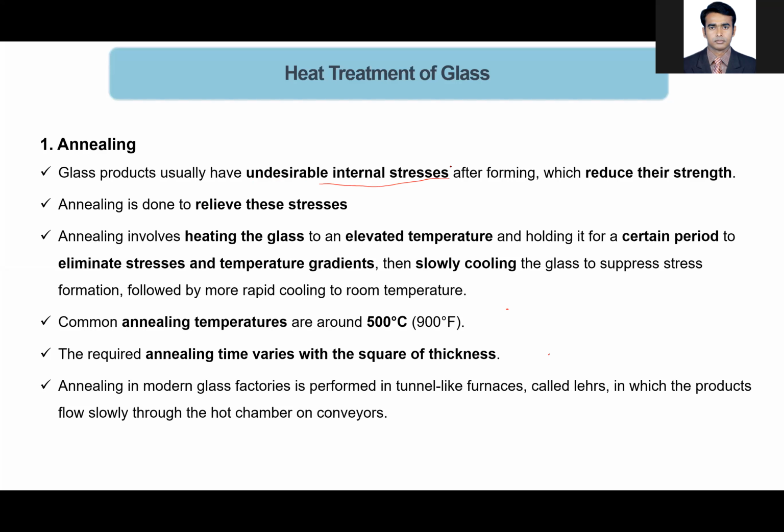Actually, the glass is an amorphous material. Okay, and it doesn't have the continuity of the molecules inside the material, and they're distributed randomly, and that also causes undesirable internal stress. But when the glass is subjected to the compressive force or the shear force, and after solidification, that force actually remains inside the material, and it causes the internal stress. That means sometimes that internal stress becomes the cause of failure. That means the failure actually starts in those points where the internal stress is much higher.